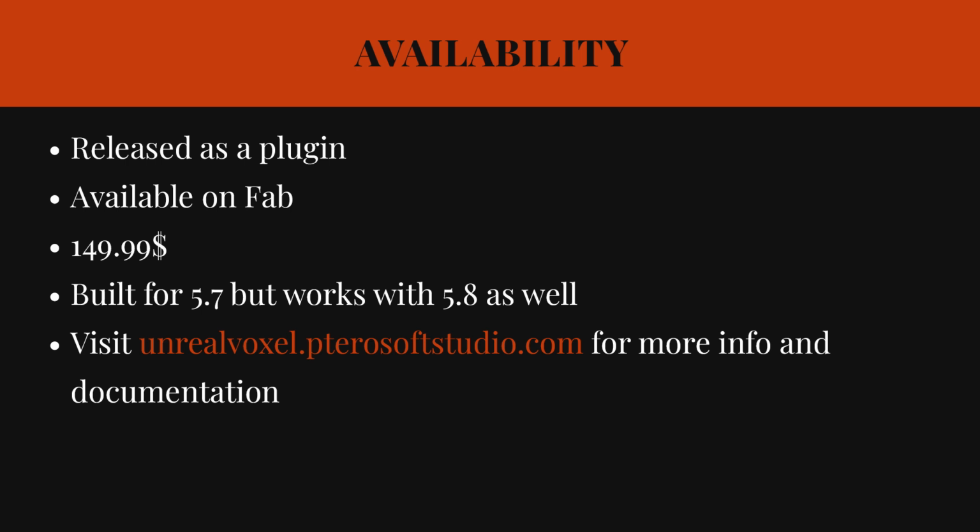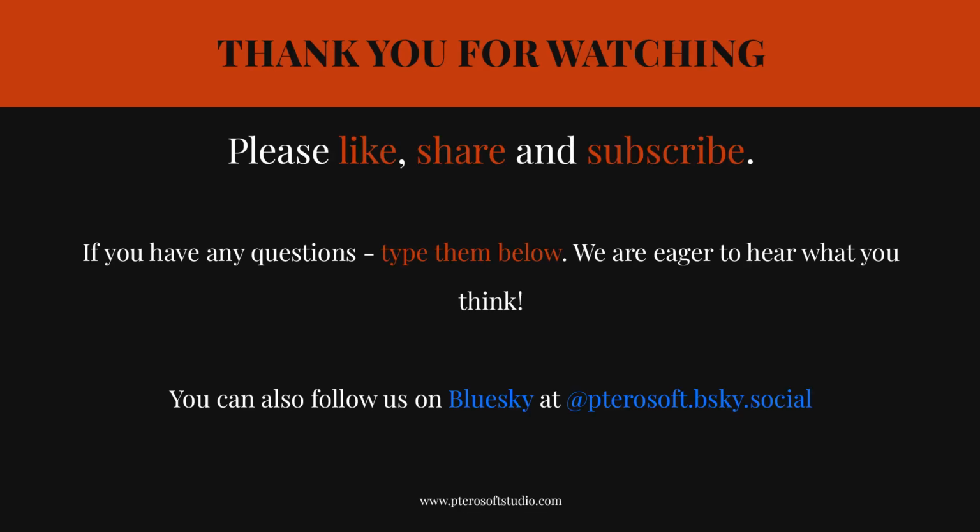That's Voxel Global Illumination. Why we built it, how it works, what it costs in frame time, and where to find it. To recap in one line, it's a voxel cone-traced GI system for Unreal Engine 5 that trades some of Lumen's flexibility for meaningfully better performance at high resolution, with hardware ray tracing layered in specifically where reflections need it most.